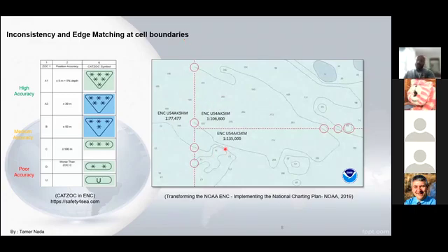is 3 cells. When I say cell, that's an ENC chart, and that's one ECDIS display. As we can see, cell 1, cell 2, and cell 3 are all the same scale, scale 4. But what we see over here is inconsistency in the contour, and over here the contour is missing between these 3 cells. Whenever a mariner sees something like that, that gives him poor confidence in the chart.